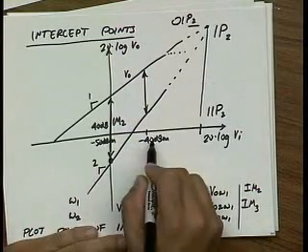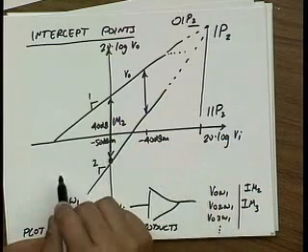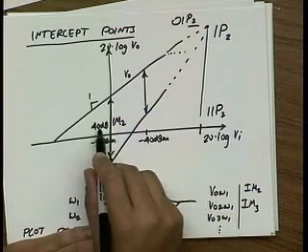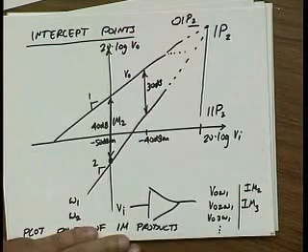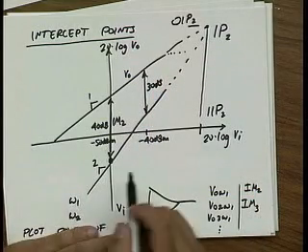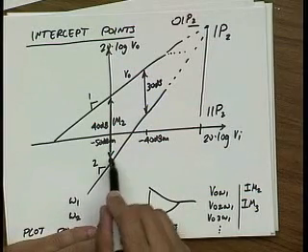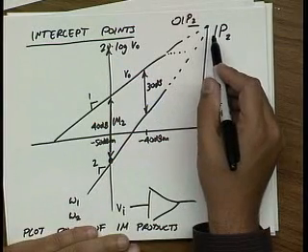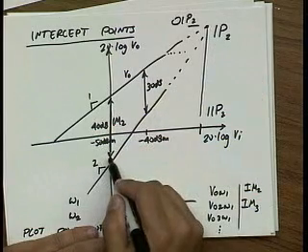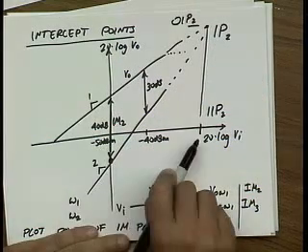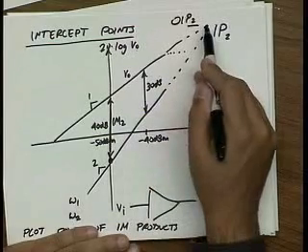So if I change the input power by 10 dB, the IM2 will also change by 10 dB. So here, instead of 40 dB, it'll be 30 dB. And so if you know the IM2 at any given point, it's very easy to calculate how far you need to go to get to the intercept. If I'm at 40 dB here, right, 40 dB difference, I just move 40 dB forward, and boom,